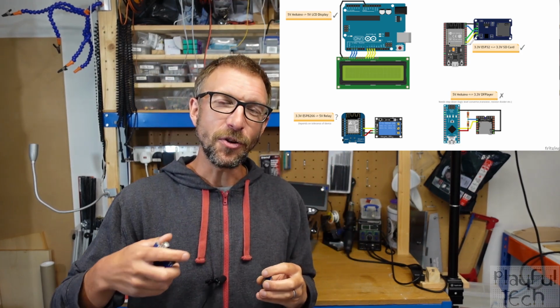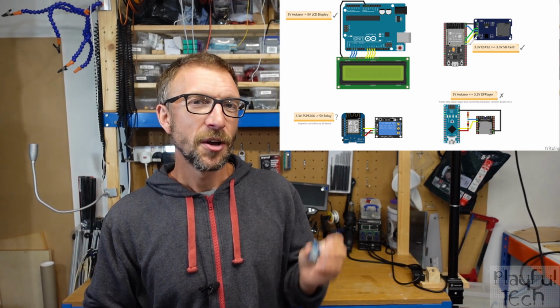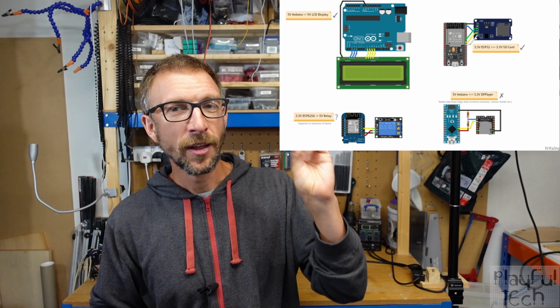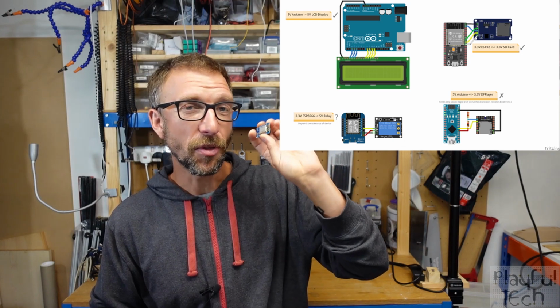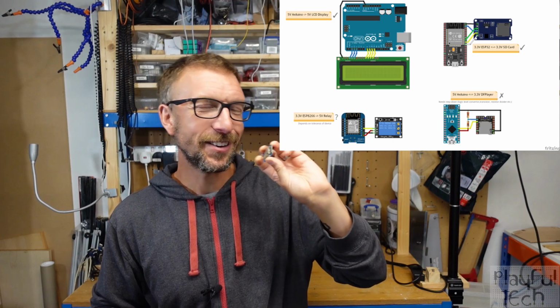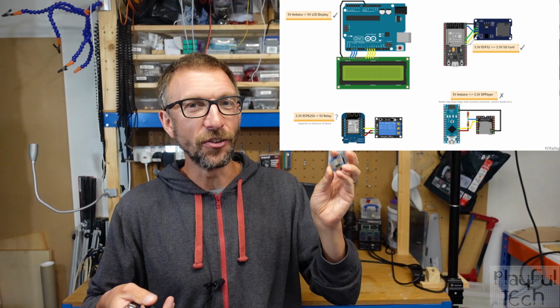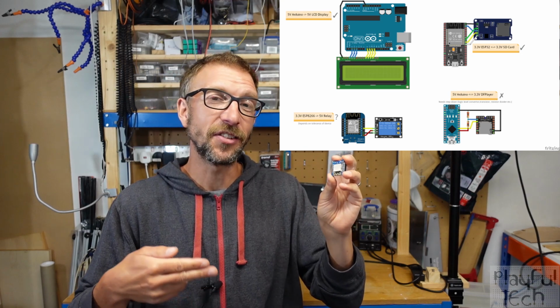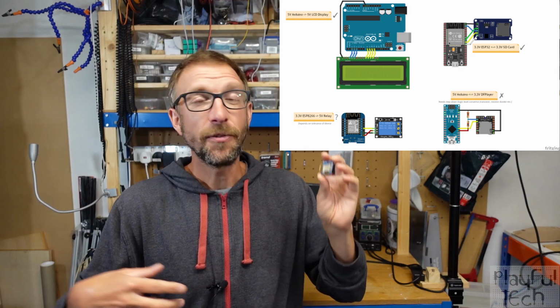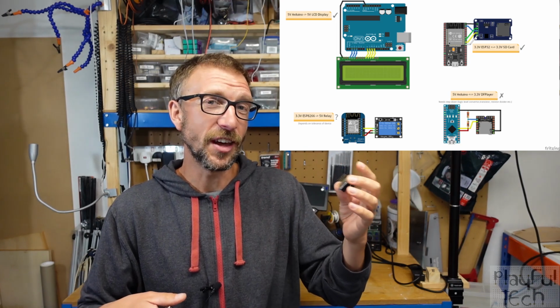But what about if you wanted to control a 5 volt logic device, but you were using a controller that only operated at 3.3 volts? Well, that might be okay. It depends on the device. As I mentioned earlier, there is some tolerance in what is acceptable as a high signal. A 5 volt device doesn't need to see exactly 5 volts to interpret that as high.